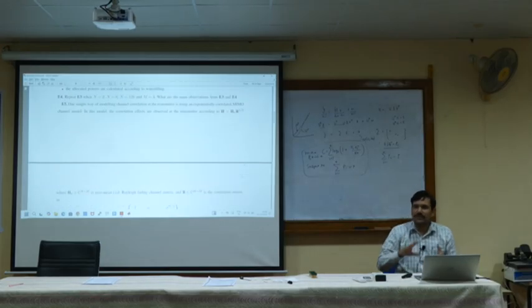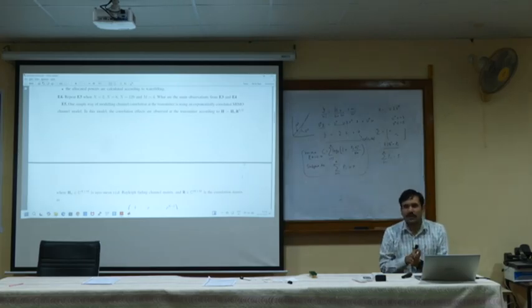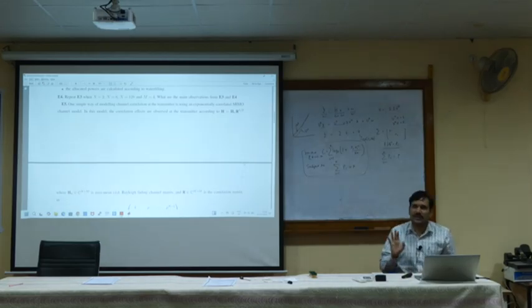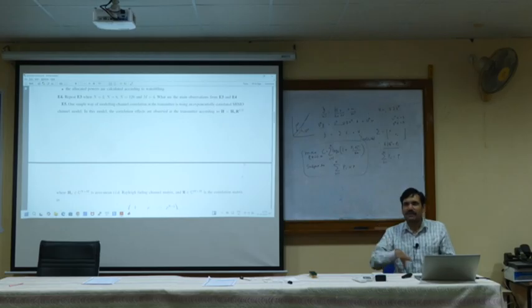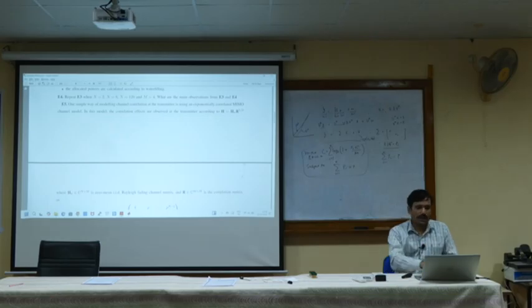Here we generate the channel H using these two matrices. H_W is a CN(0,1) matrix, a complex Gaussian matrix with zero mean and unit variance. R is a correlation matrix, given below, and we multiply by that R matrix. So the H matrix will have some correlation.